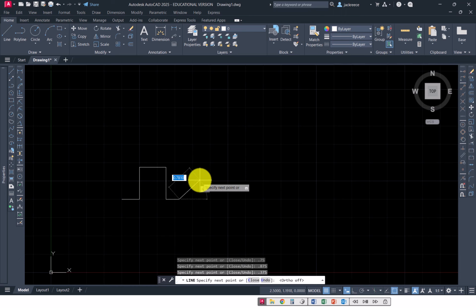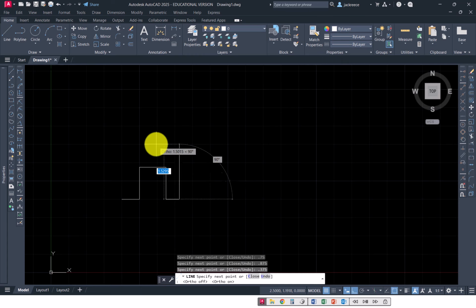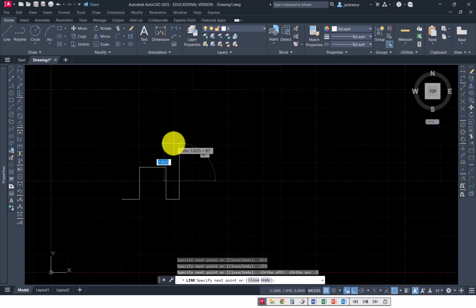Okay, now I'm going to depart from the way the drawing is, and I'm going to jump on over to the right hand side there and show you the polar to get the angles. I turned off ortho mode. Well, I need to leave it on. I've got to go one more, so we'll turn that back on and go up 0.5. And now we've got a polar mode, so I'm going to turn off my ortho. And it's 35 degrees, which is kind of an unusual angle.